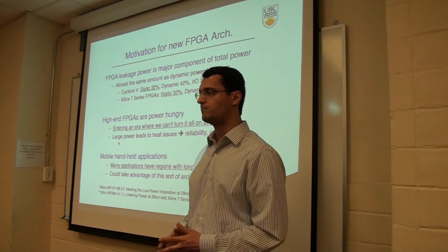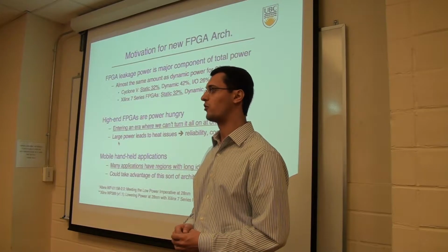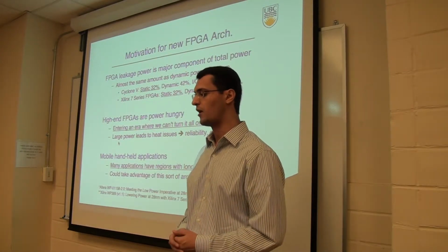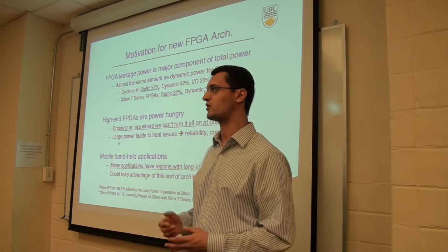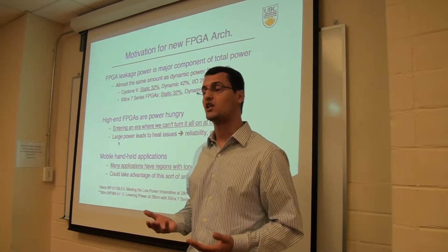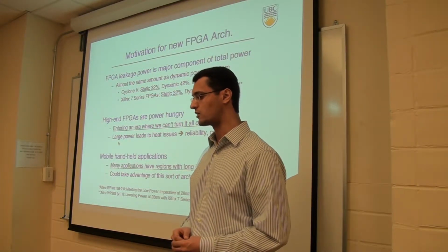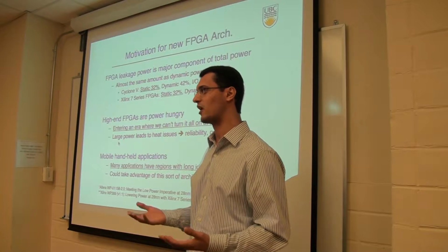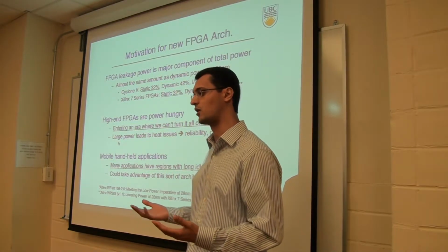We know that FPGA leakage is becoming more and more important as we scale the technology. In recent technologies, as shown in some white papers from Xilinx and Altera, static power is becoming the same amount as dynamic power, which is interesting because dynamic power is not the major component of power consumption anymore.